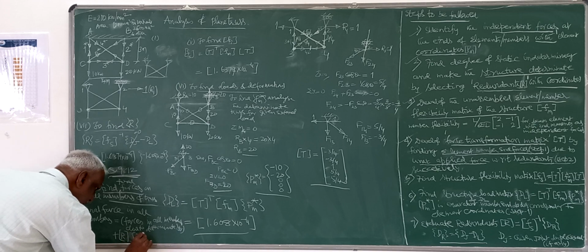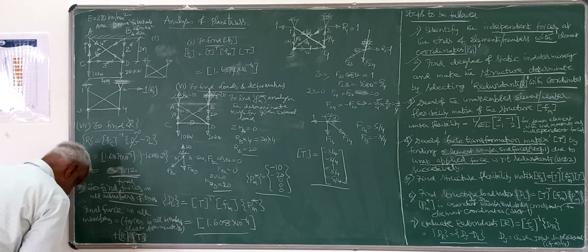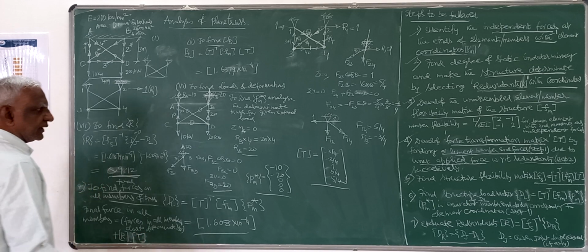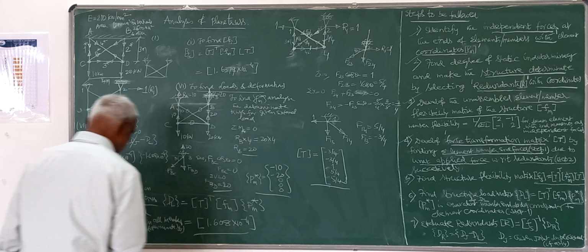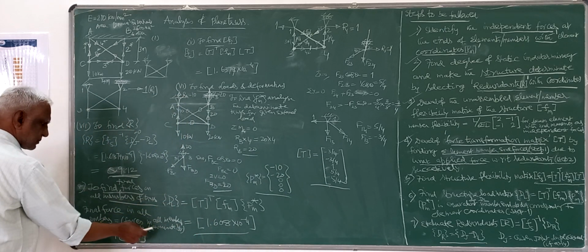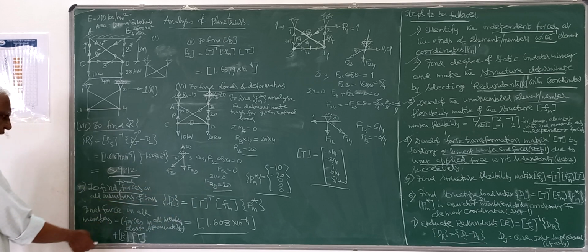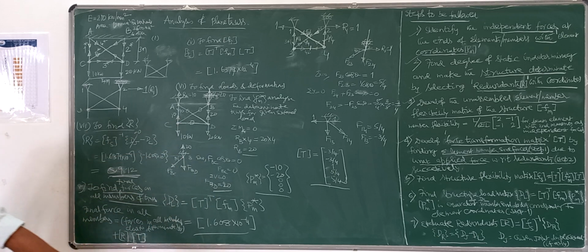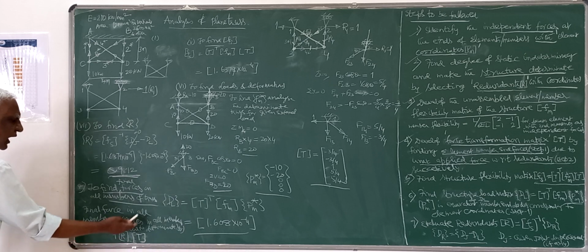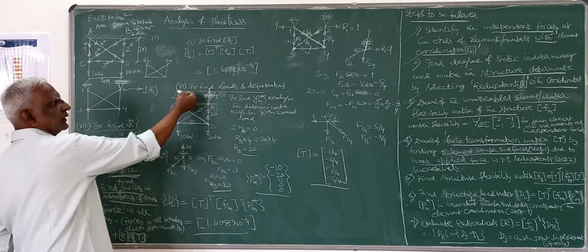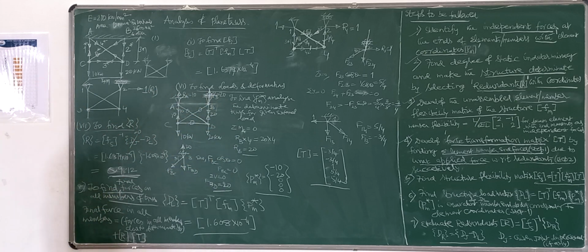So whatever T you got, that you multiply by R. That is 0.9812 you got there, into the T matrix. That you multiply it, add it to the forces what you have determined in the basic determinate structure, you will get the final forces.